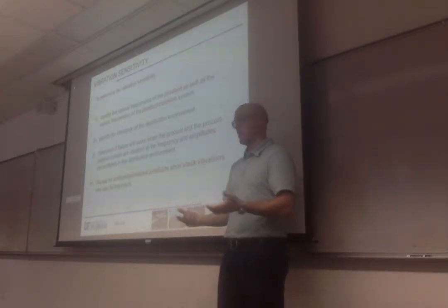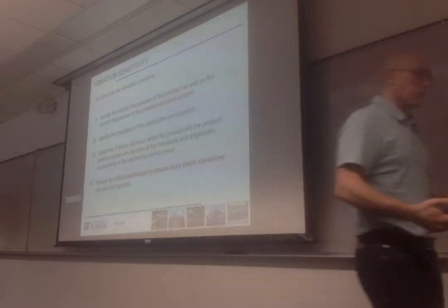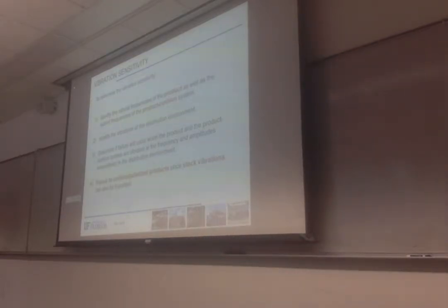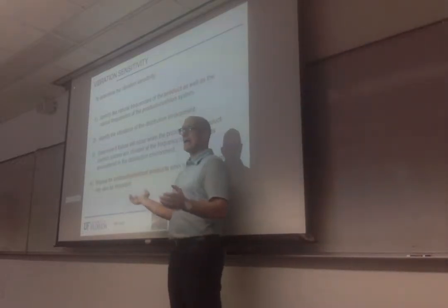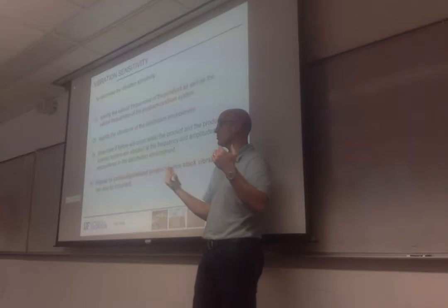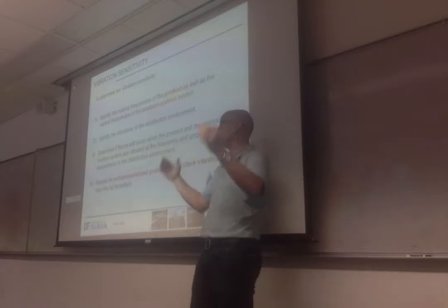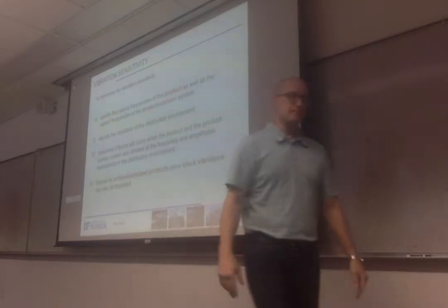humidity as well. See if you were to expose the product, the pallet, to a more humid environment, and then shake it. That will change the stiffness of the board, and they may fail, or they may act totally differently. So these are important things to deal with. It's also important to use the right pallet, because if you use a different pallet, that vibration is also going to be different. The pallet also acts as a pretty stiff spring, but if you have something heavy on that pallet, it will behave differently.